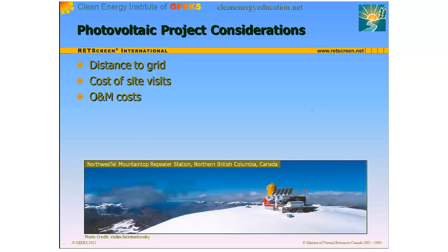Photovoltaic systems have high initial costs and low operating expenses. In contrast, many competing power sources, such as gensets, are initially inexpensive but have high ongoing costs. It is critical, therefore, that operation and maintenance costs, and not just initial capital costs, be included in any comparison of different power systems. While PV systems rarely break, they may fail to provide power if there is a longer than normal period of especially overcast weather.